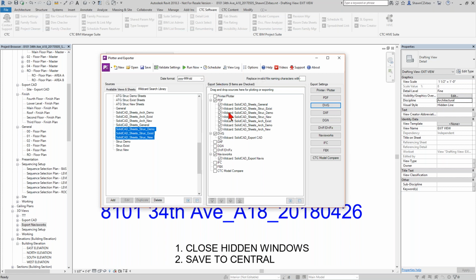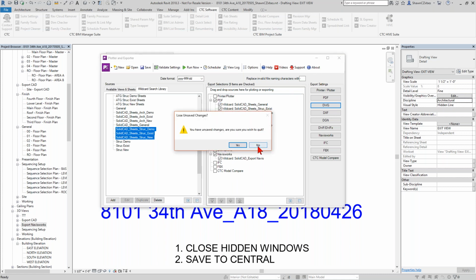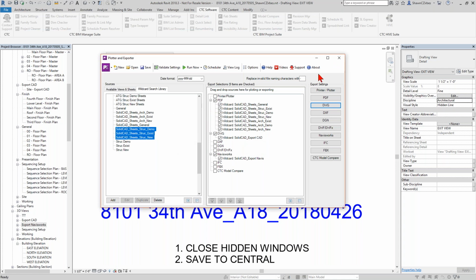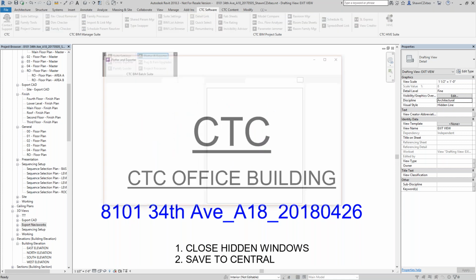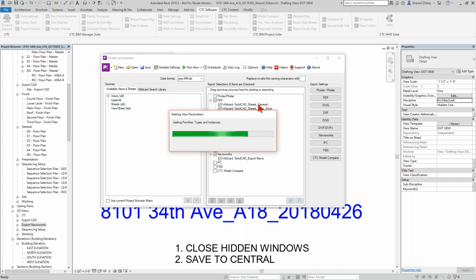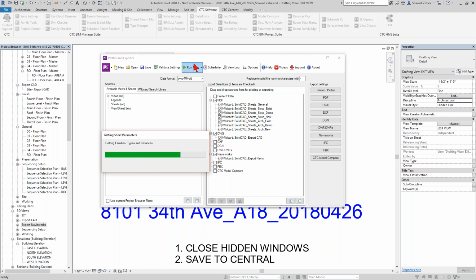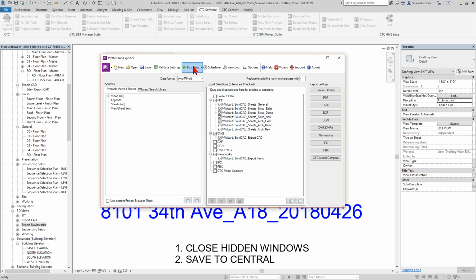In a lot of cases, we're doing these things all entirely manually. But you saw earlier, when I first opened up this tool, I should hit yes to that. Yes, save my settings. When I open up this plotter exporter tool here, it's going to remember my settings from last time. It loads up all the things that I've asked it to do, and I can simply click Run Now and walk away and let it do a thing. Or, again, I can schedule it for some after-hours processing using my saved settings for these rules and telling it which files to apply those settings to.